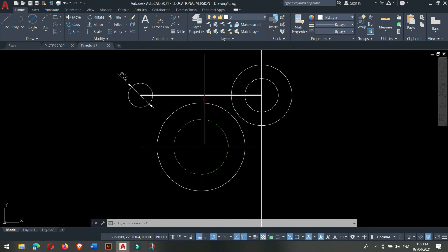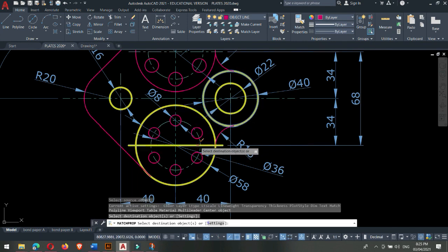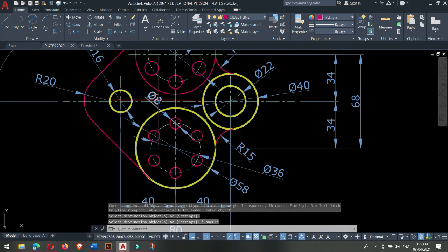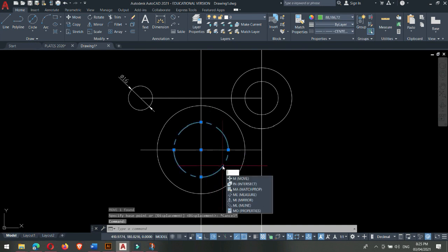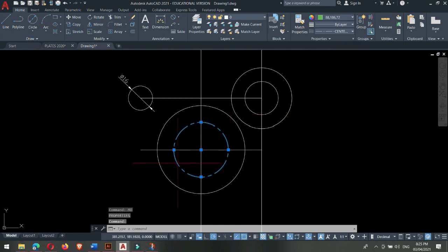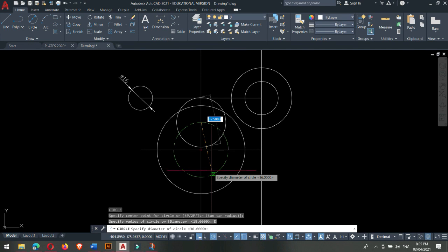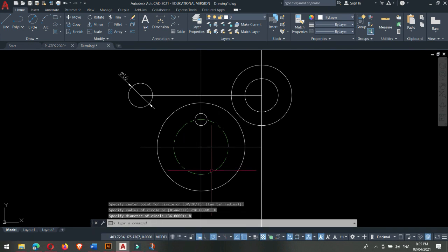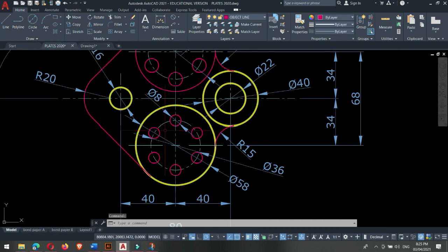From this circle, we're going to create those little circles with the diameter of 8. So we just created these and this one. Alright, so the diameter is 8. I'm gonna create a circle here. I'm gonna change the line type scale first. It's MO. Change it to 0.2. And we're good. So the first circle goes down here and the diameter is 8. Enter. I'm not gonna create little circles one by one. You can see at our reference, the circles are actually 1, 2, 3, 4, 5, 6.